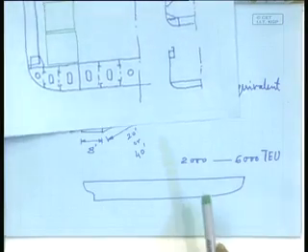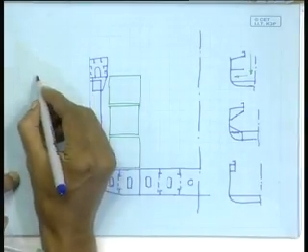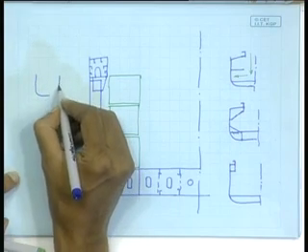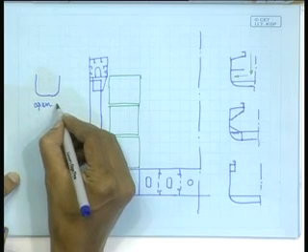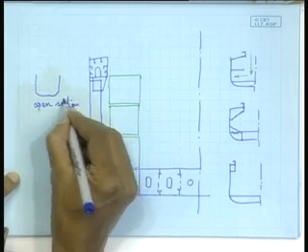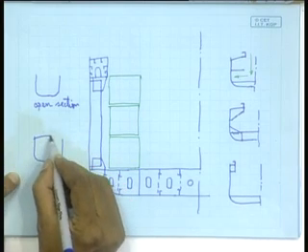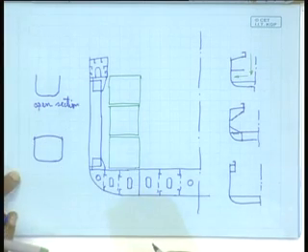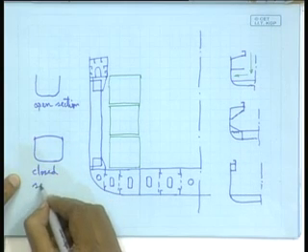means with increasing length, it is not only becoming more slender and your bending moment is increasing, your torsional strength is decreasing drastically, because it is becoming a case of open section. This is what is an open section. It is somewhat equivalent to a case of open section. Just the opposite of it is what? Obviously a closed section, and that is the oil tanker, right.